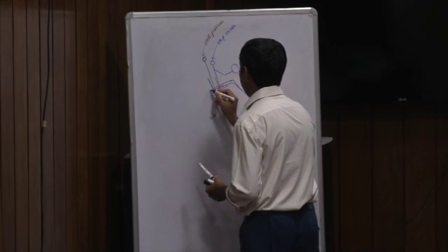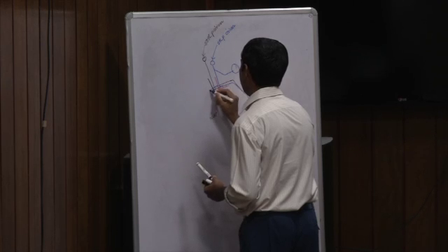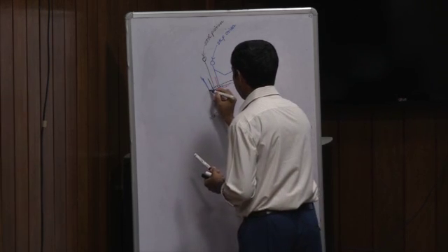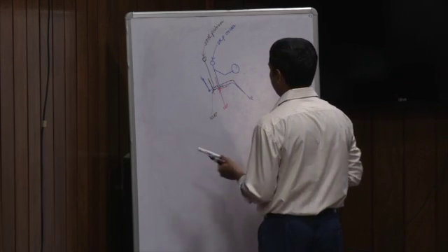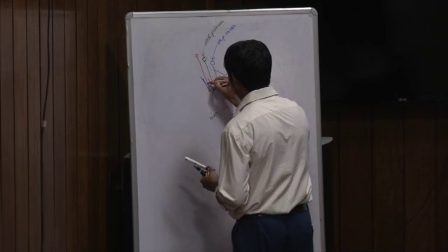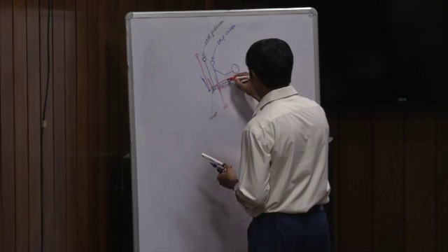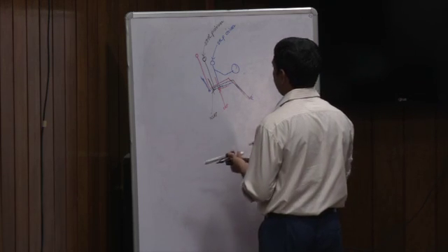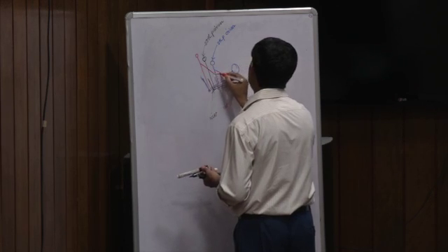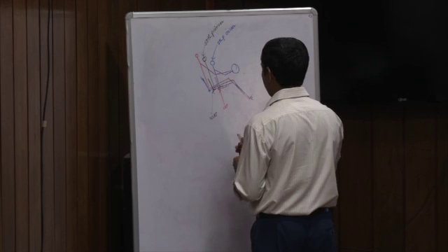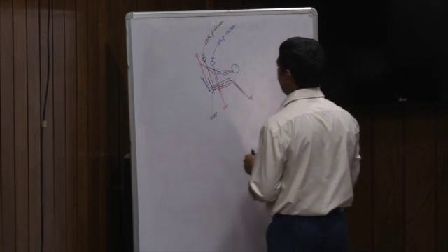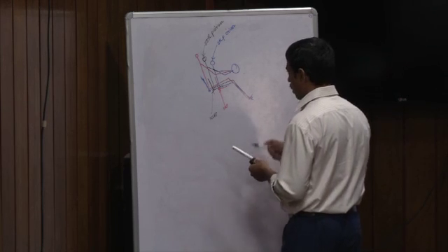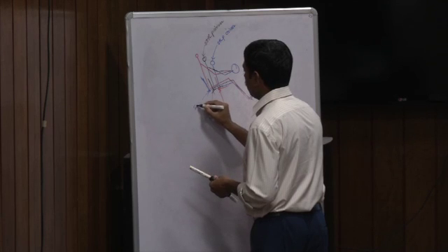Then if the seat is moved further for accommodating the 95th percentile driver, if this is the seat position, in this case, if we imagine this is the 95th percentile driver, then this point will be SGRP.